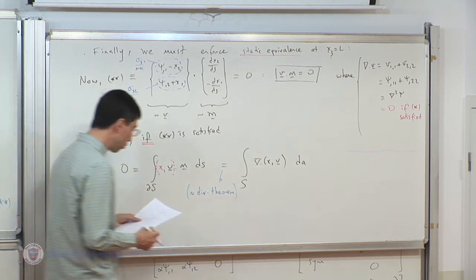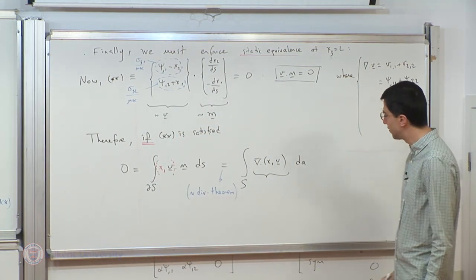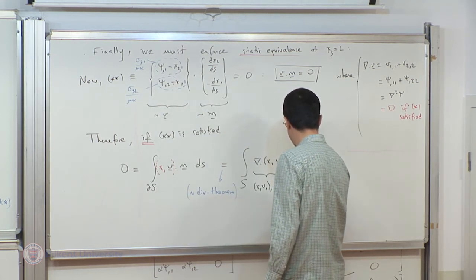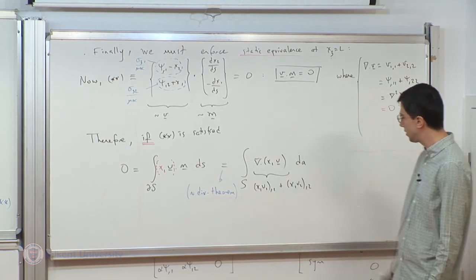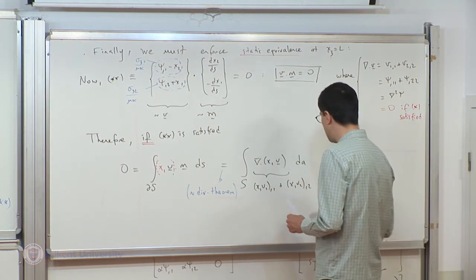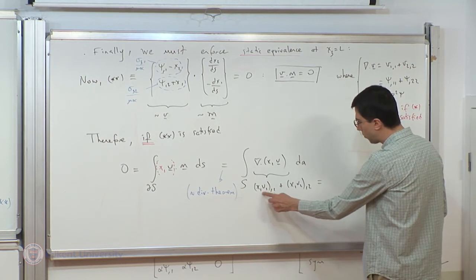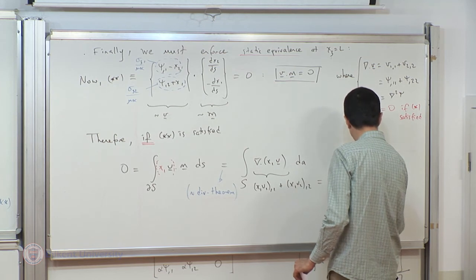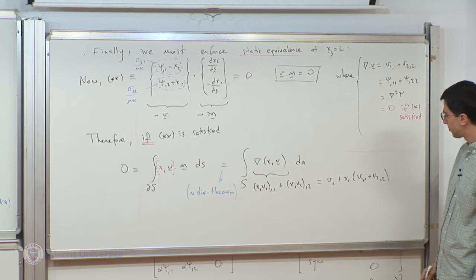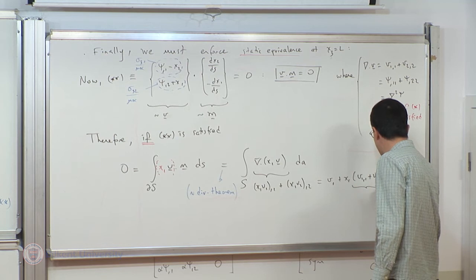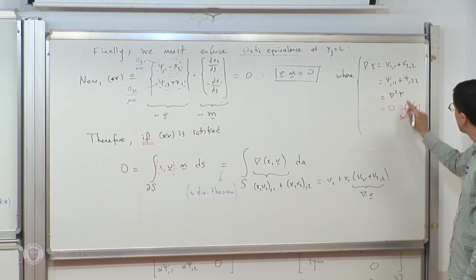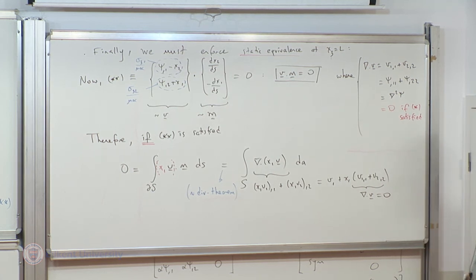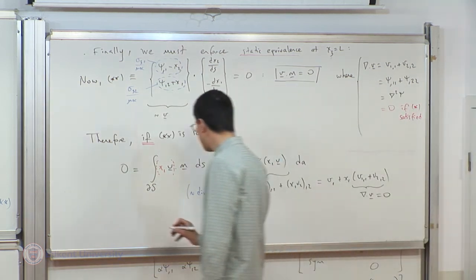Okay, so that's good. Let me work out what this derivative is. It's the first component of the vector, comma 1, plus the second component of the vector, comma 2. So x1 v1 comma 1, x1 v2 comma 2. Now, if you calculate the derivatives, then x1 comma 1 leaves a v1, and then x1 times v1 comma 1 plus v2 comma 2 is going to appear. The term in parentheses is nothing but the divergence of v, and the divergence of v is equal to 0 by the requirement of equilibrium. So this term died away, and I'm only left with v1.